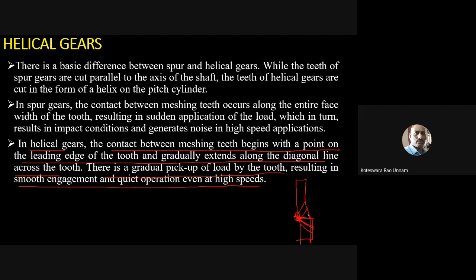Because of this gradual engagement of the teeth, the load is not suddenly applied, it is gradually applied, and because of this gradually applied load, it will be a smooth operation, and that means there is no noise even if you operate these helical gears at very high speeds.